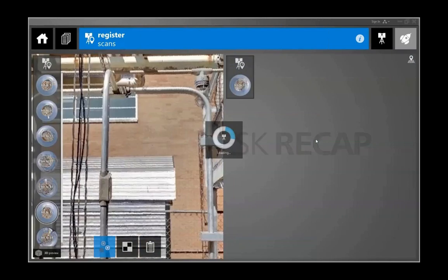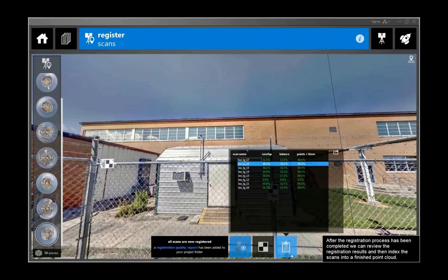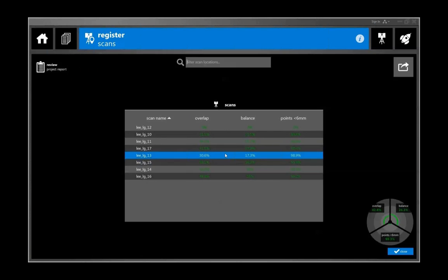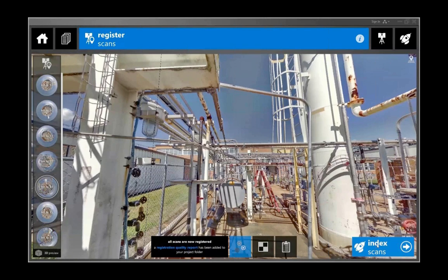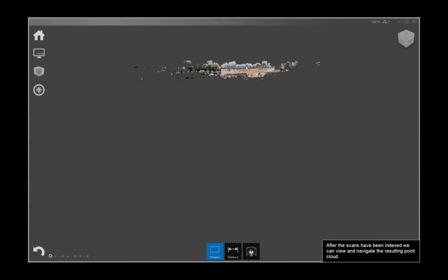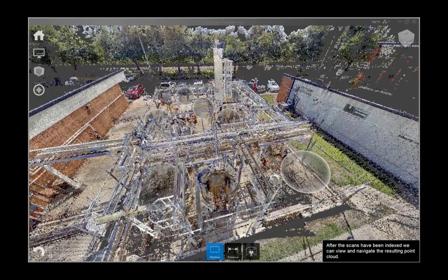I know a few of my customers are actually collecting subsea data using things like sonar and other acoustics to capture bathymetry data if they're doing maybe some subsea work, or if they're doing some piers, or really any type of work that happens either near or under the water. So we can really accept different types of files into ReCap Pro. And what you just saw there was actually a QA/QC report of the quality of the data that we've registered within ReCap Pro. So once we've registered the data in ReCap Pro, we can navigate around the point cloud.